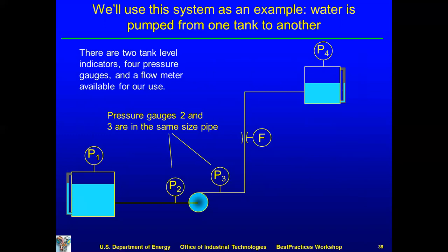And then you'll have the height of the water column in the suction tank to consider. We've got a couple of slides on this. Moving on down the piping system, we're showing a suction gauge at P2, and that gauge is at some elevation off of, say, the floor or a conveniently selected datum.